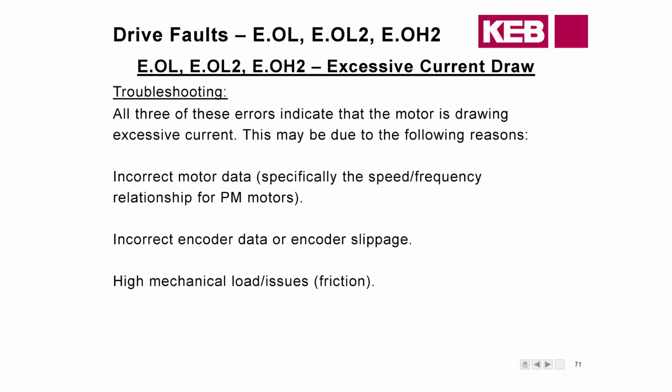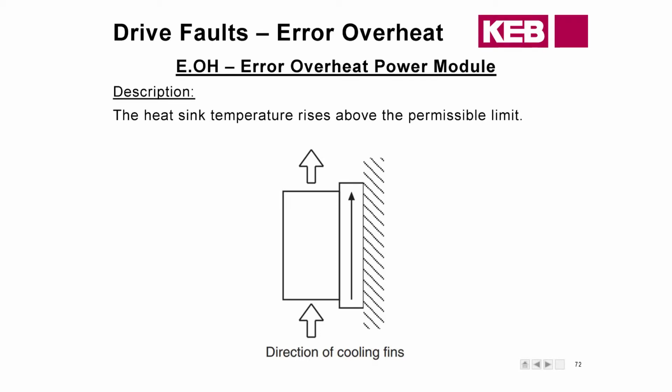Error overheat, this is going to be the heatsink itself is too hot. The transistors, they may have switched the carrier frequency down to take care of that, and you might start hearing that switching frequency. But yeah, the heatsink, it's too hot.